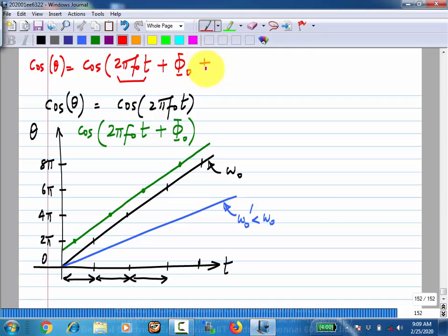And then plus, let's say I have some other function of time, which is not linear obviously, because if it was linear, if it was a straight line, I would absorb it into this and change f naught. Okay. So for now, let's assume that all the straight line variation, the linear part is absorbed into this, the offset is here. So this phi of t, typically, I mean this is not necessarily true. Sometimes we take this phase, this is known as the additional phase deviation.